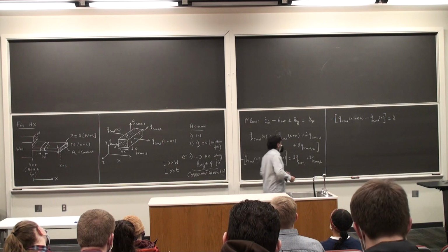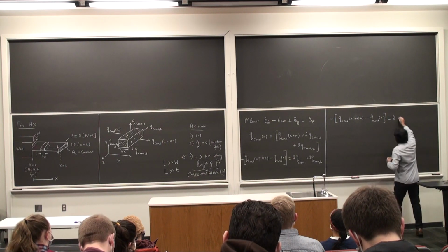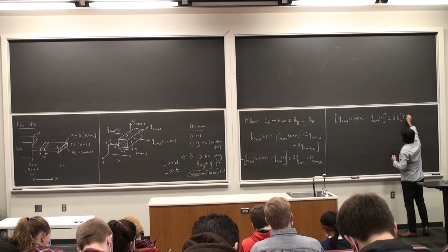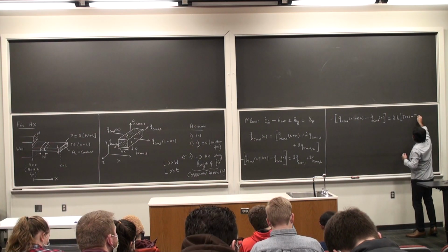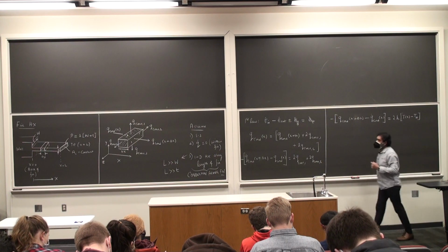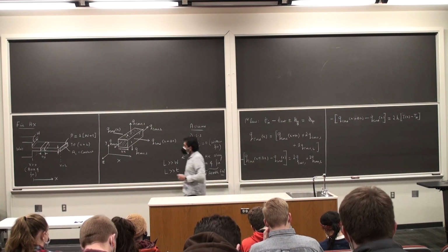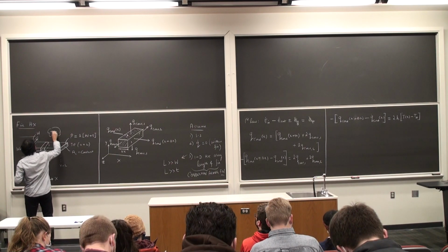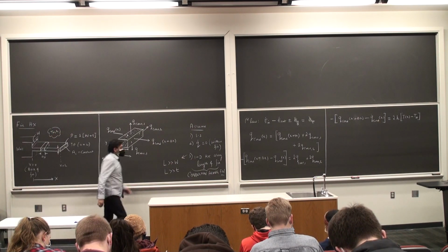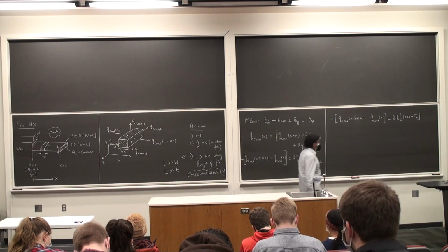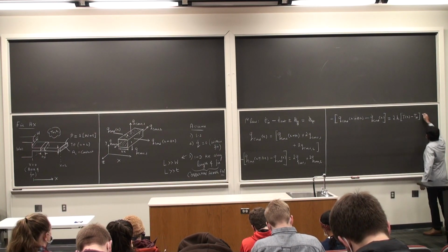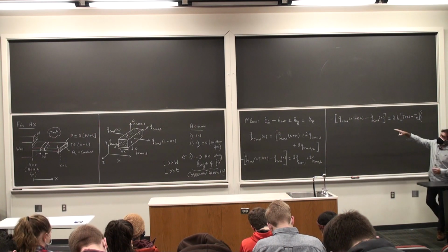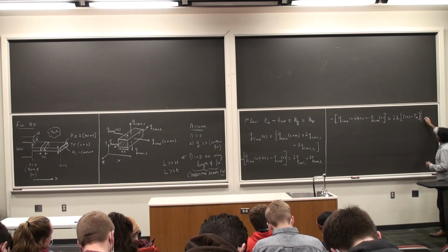So this is 2 times h delta T, T of x minus T infinity, where T infinity is the ambient surroundings everywhere. Then I'm going to have 2 things. The first area is the area of the top surface, which is the width times delta x.